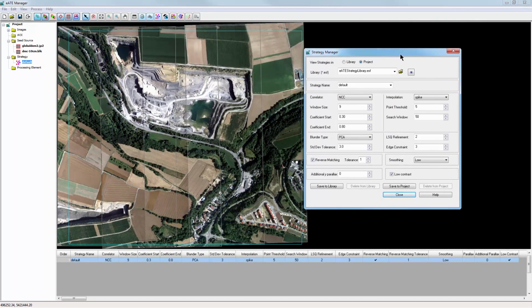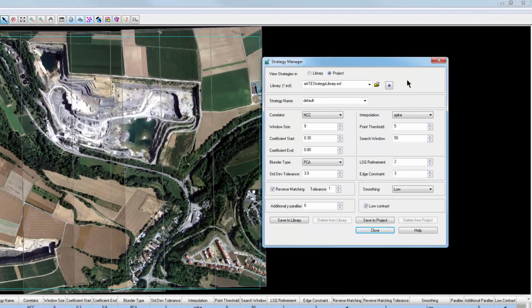As a general rule, it's a good idea to leave most of the default values. These values have been determined by engineering to optimize results. However, in some cases, changing the interpolation settings can improve the results. The interpolation method will fill in areas of missing values with one of 3 options. Mean performs an averaging across values, region considers a smaller set of points when performing the interpolation, and spike applies specifically to remove extreme values.